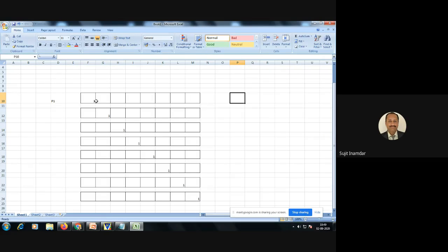So one can think that if for the first stage this is 1 and all others 0, it is equivalent to 80H. Then the second bit or the LED will be 1 and all others 0. That means it is equivalent to 40H. Is it? Because if you are writing all other places 0, so 0 1 0 0, that means 4, and these zeros mean 0, like that.